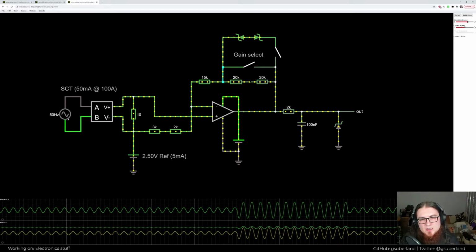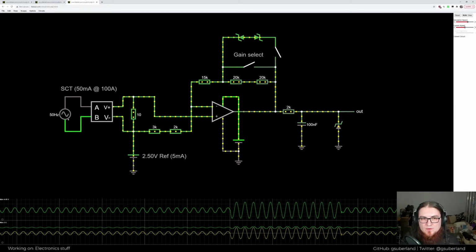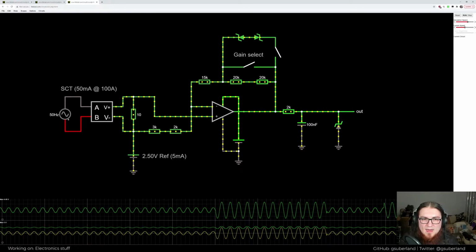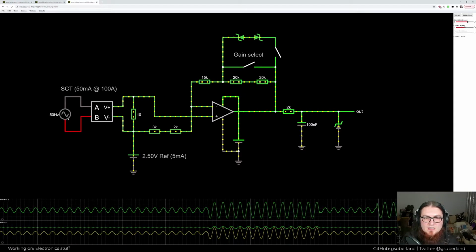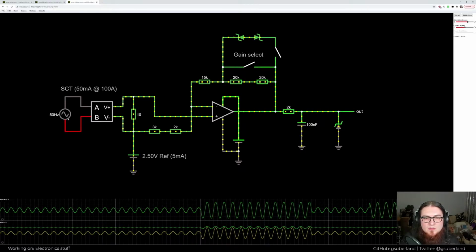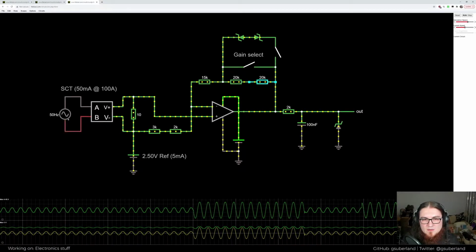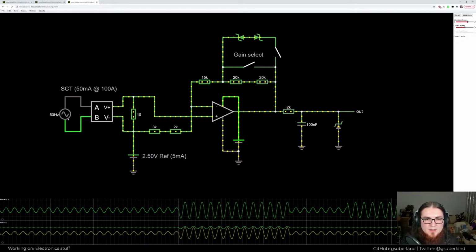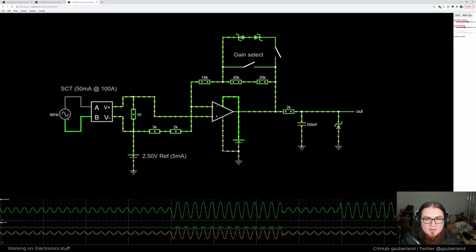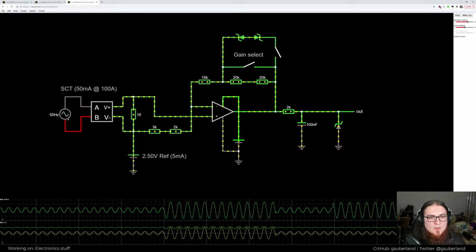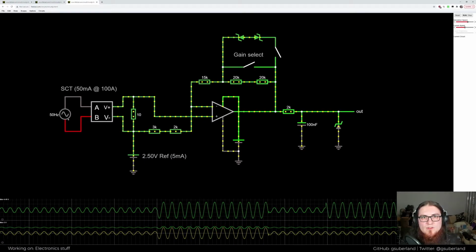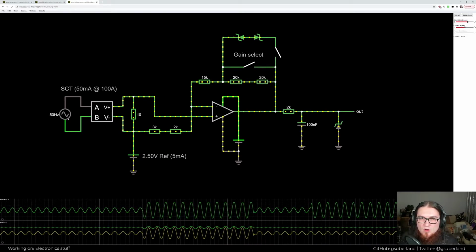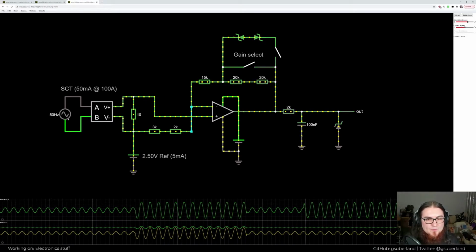So this then turns this total resistance up here. It adds an additional 40k to the 15k. And then when you add all of it up, you've got 5 plus 15 is 20. That brings it up to another 20, so that's 60. 60 over 5. Effectively, you get a gain of 12. Or 3 times the original gain, which is good. So obviously it was 4, and now it's 12, so that's 3 times as much.